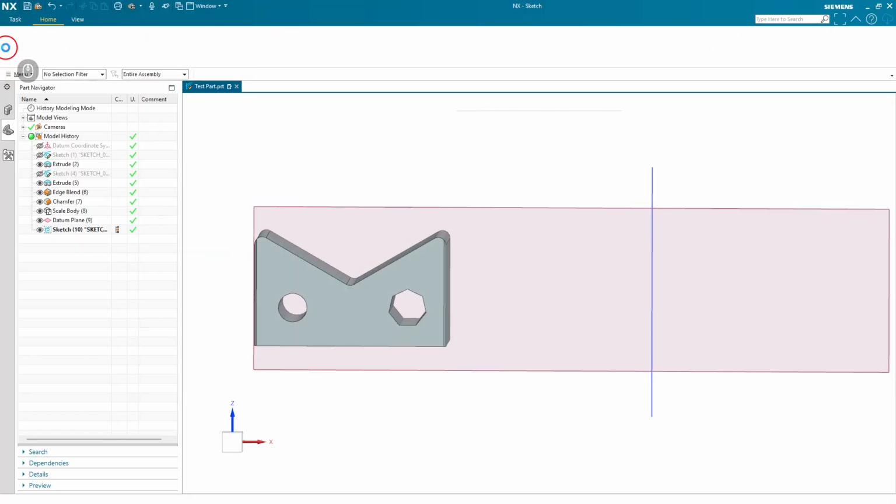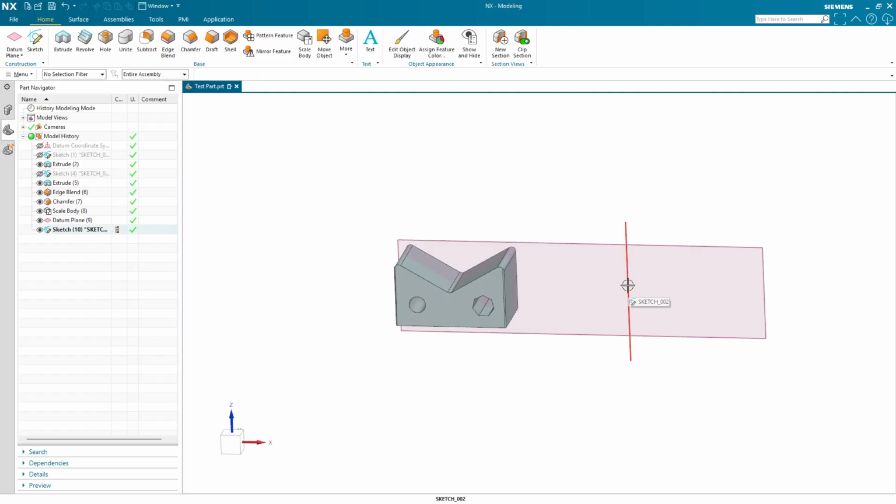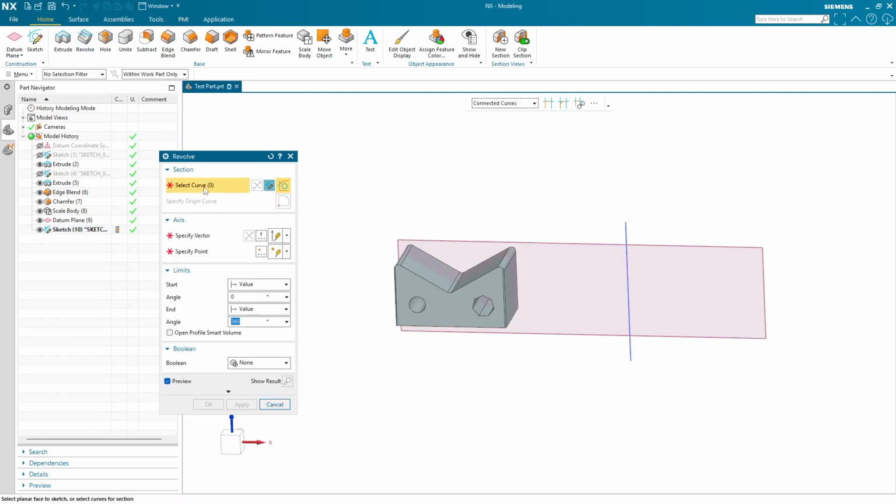And now when we close this, we can pick that as our axis of rotation once we're in the revolution menu. So if that ever happens, you hide something as a construction line you didn't mean to, just go back in, right-click it, and you should be able to convert back to a solid contour line like this instead of a construction line.